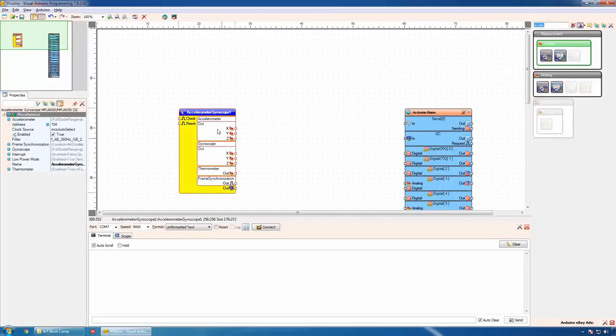The module sends both acceleration and gyroscope rotation data, and it also has a temperature sensor. We can send the data in the form of a packet or structure through the serial port, but in this project I will demonstrate how you can print formatted data in the serial terminal.